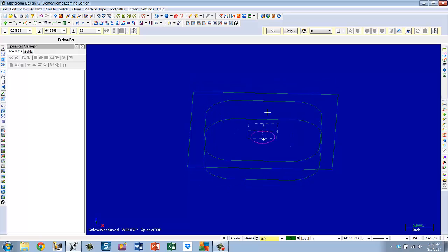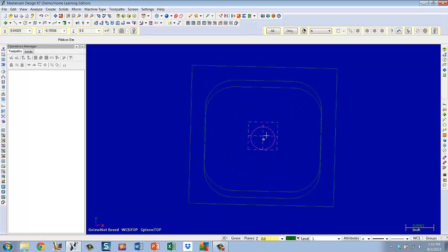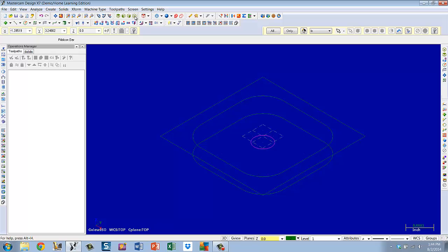I'm going to push down and pivot again to make sure that's what I want, and it is. So I'm going to go to the isometric view now. So here we actually copied the geometry instead of drafting it down and then putting all of those edges on them.